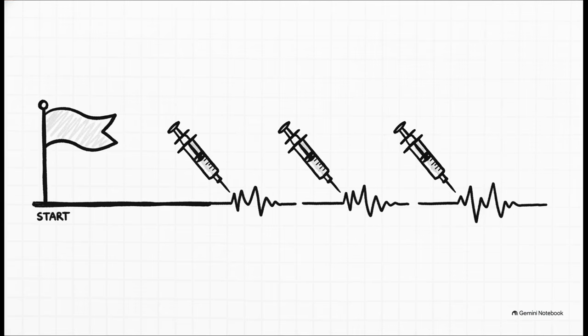You see that hashtag 20? That hashtag 20 is a delay command. It tells the simulator, hey, wait exactly 20 simulation time units, which we already know is 20 nanoseconds, before executing the next line. So right at 20 nanoseconds, input Y changes to 10 in decimal. Then it waits another 20 nanoseconds, changes X to 10, and so on. We are injecting specific stimuli into our adder exactly when we want them.